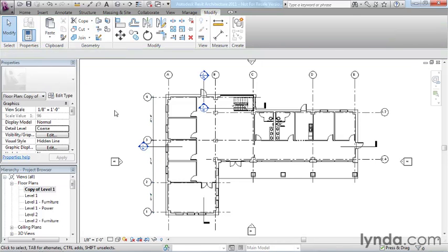All I want you to understand here is the default behavior in Revit is that annotation is always view specific, and the model, on the other hand, shows in all views simultaneously. And we saw plenty of examples of that in the previous movie. The next concept that I'd like to share with you is the overall hierarchy of the elements themselves. It branches down into a 4-stepped hierarchy.